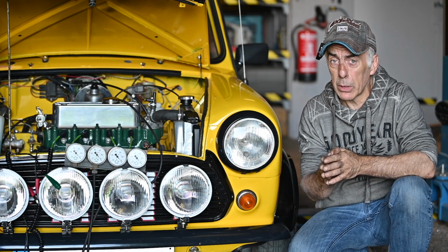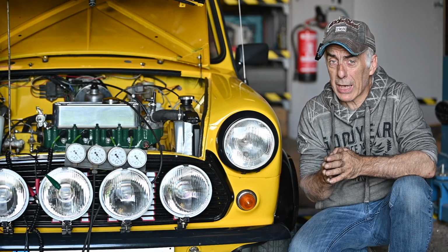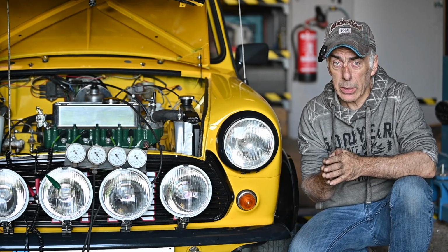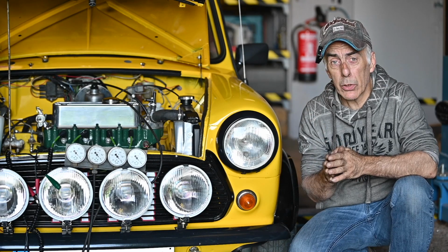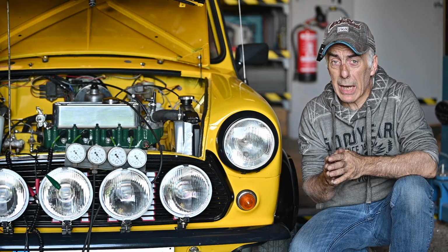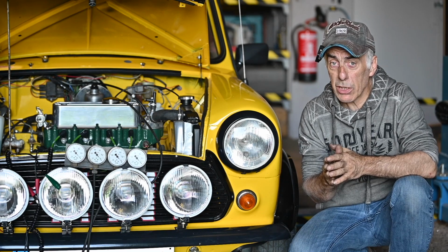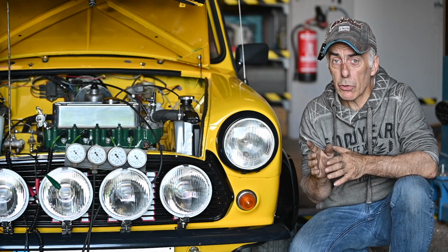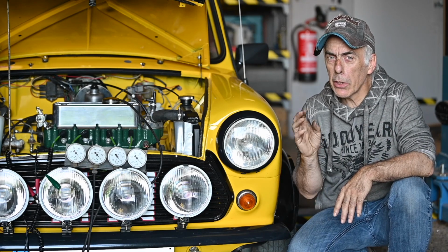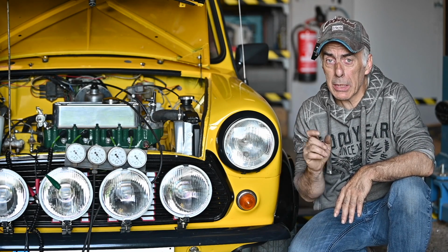I've seen that before. So you might actually want to check the marking on your flywheel if you have access to it. On the Mini, there is a way to do it. There is an inspection hole that you can look through and find out the markings on your actual flywheel to identify true top dead center. So on the Mini, it's always good to open up that inspection hole.